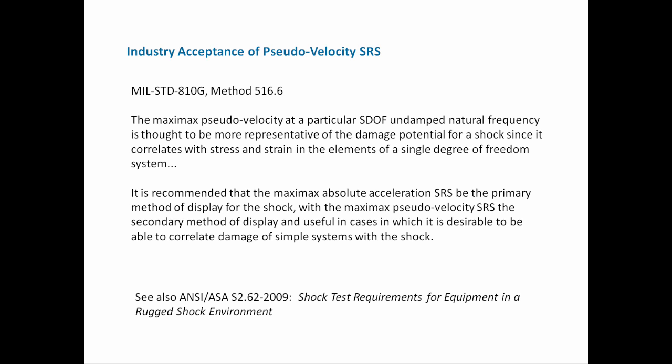So the paradigm has not changed yet. We're still primarily using absolute acceleration as the primary metric for SRS, but there is some consideration being given to pseudo-velocity. And personally, I like the one-size-fits-all method of the tripartite or four-coordinate plot method, because maybe we should specify all our specifications in four-coordinate plot, because that has something for everybody.